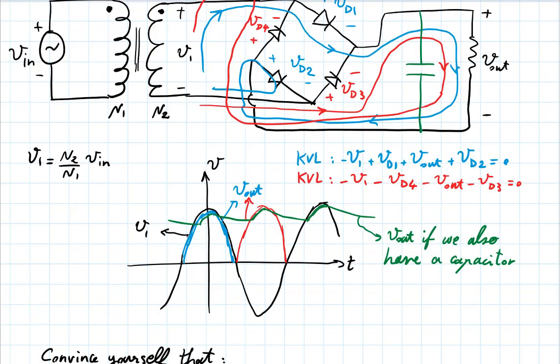Well, look at what we have accomplished so far. What we have accomplished so far is we've taken an input that's a sinusoidal curve, and we have managed to turn it into something that has a substantial positive average with some fluctuations around it, some variations around it, that ripple. Now, that still is not terrific, right? Because if you wanted a DC voltage source, you wanted something maybe a little more constant than this.